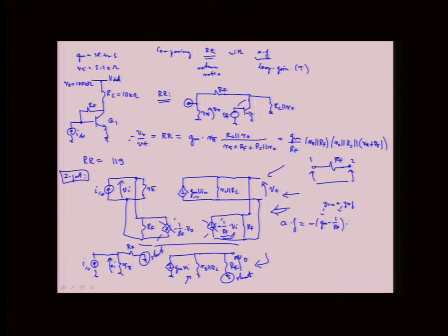And then here I would divide by Y0 and YI, but I can instead just multiply by the resistances that are seen, which is easier here. So I'll do R pi in parallel with RF. Those are these two resistors that you see. And then at the output, I have RF in parallel with RO in parallel with RC. So this whole thing is my A.